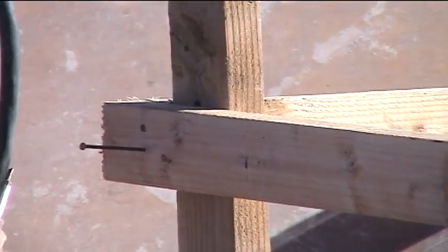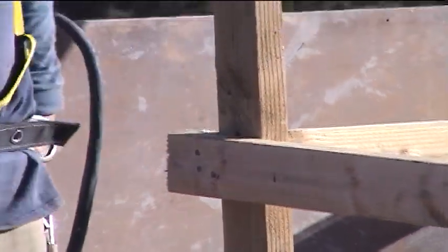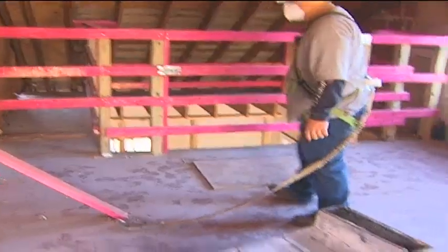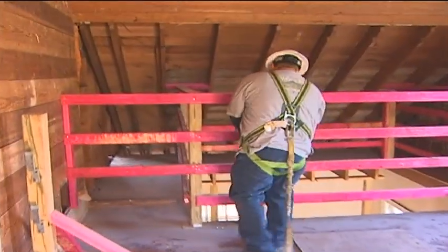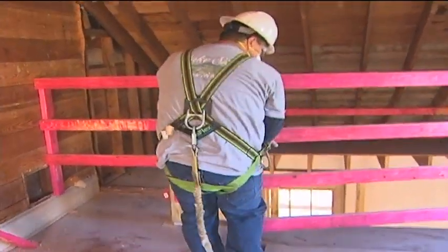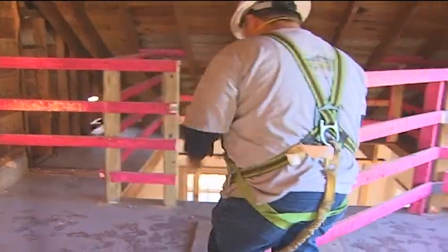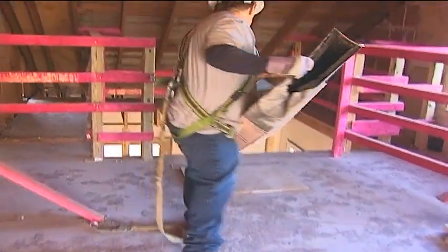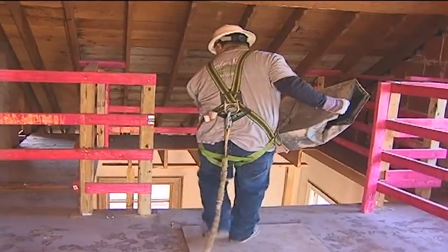Surfaces of guardrails must be smooth. Rails should not extend past a terminal post. Guardrails around access areas must have gates, or the point of access must be offset to prevent accidental walking into the area. The gate should be in place at all times, except when the access area is being used.